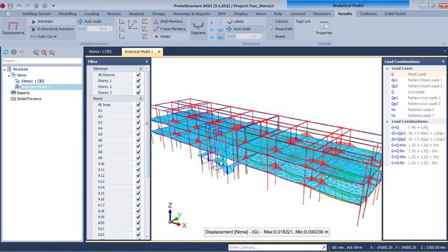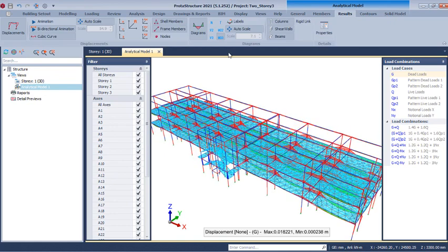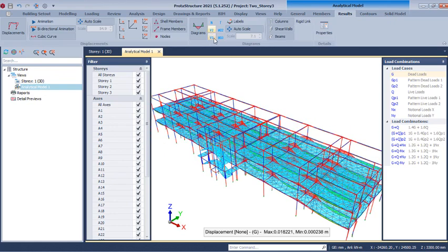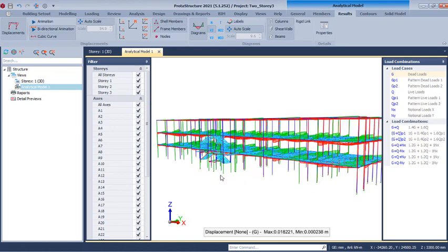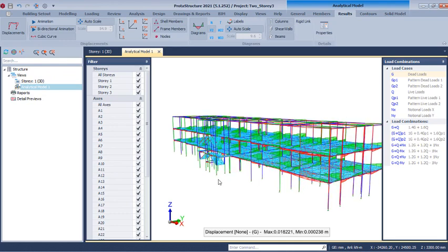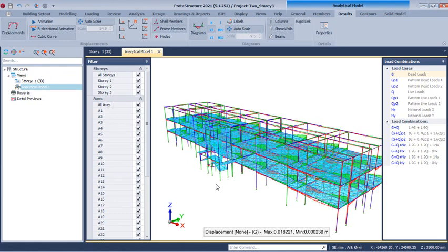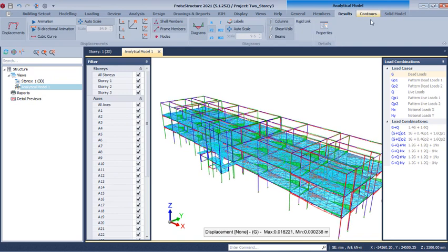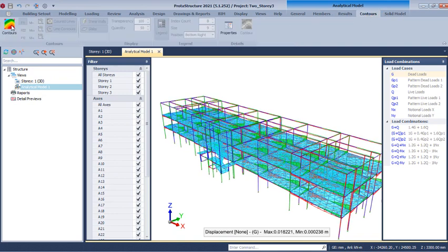All right, so you can as well check the shear force of this structure. So select them once, and then you give it some time so you can see the shear force. So these are the things you can actually add to your report successfully. All right, so if you want to check other contour, you can select in these provisions and click on this contour here. So it's going to grid and contour this slab mesh successfully.